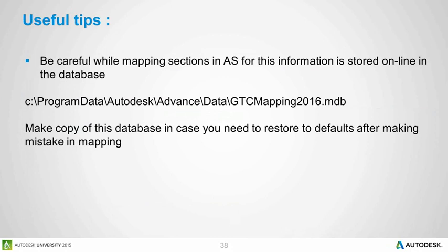And just mind that the selection of profiles you decided on during mapping is stored in the database and automatically used by Advanced Steel for all projects. It is recommended to make a copy of the default database in case you need to restore the defaults.